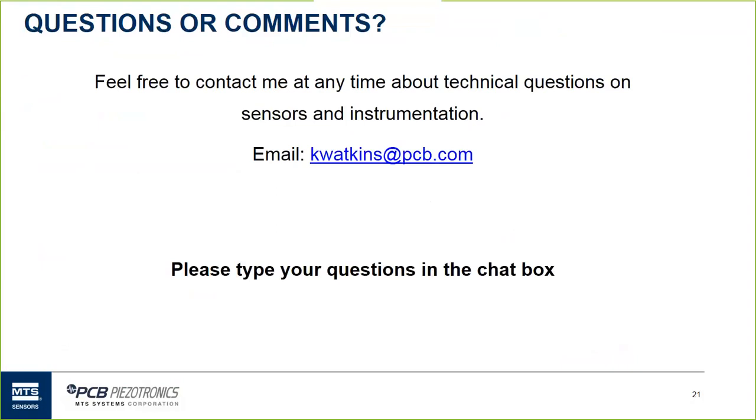And just one more. With respect to adhesive-mounted accelerometers, what adhesive is typically recommended? Looking at adhesive-mounted accelerometers, which are very popular choices and which do not permanently mar the surface the sensor is mounted to, we generally recommend a product offered by Loctite. It's model number 454, and that essentially is a gel-based super glue that's used to bond the transducer to the test surface on a temporary basis or even for some longer-term tests.